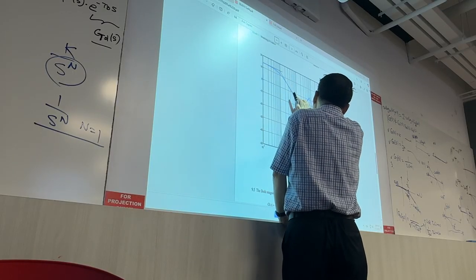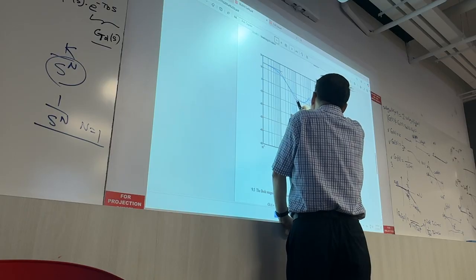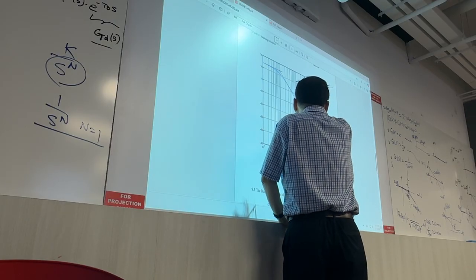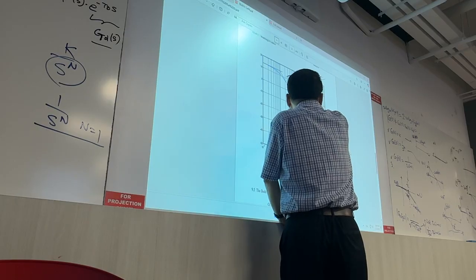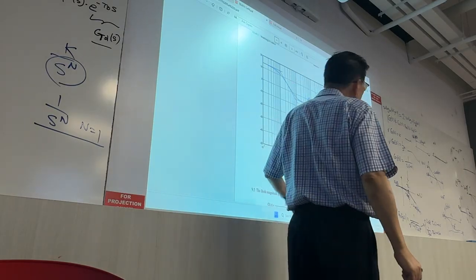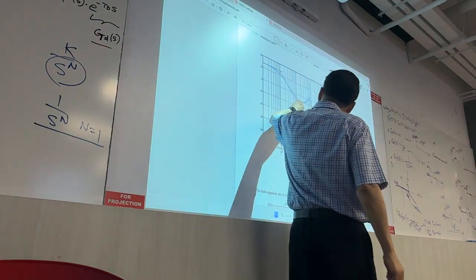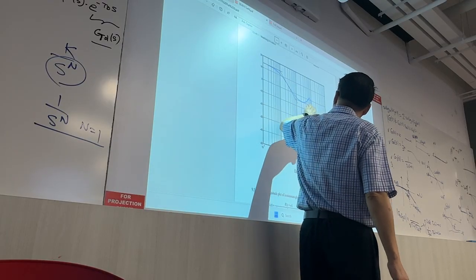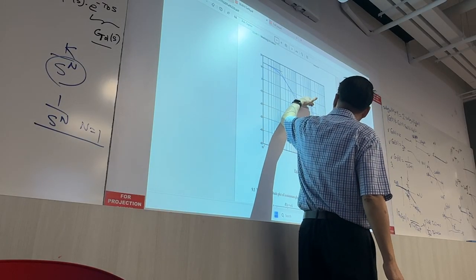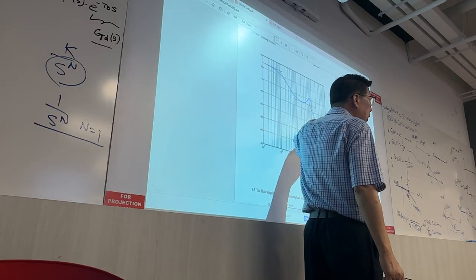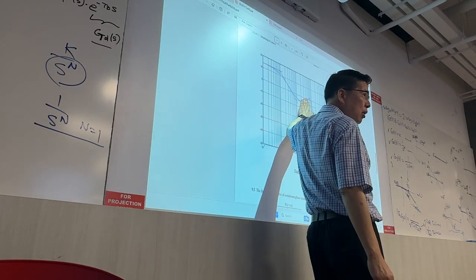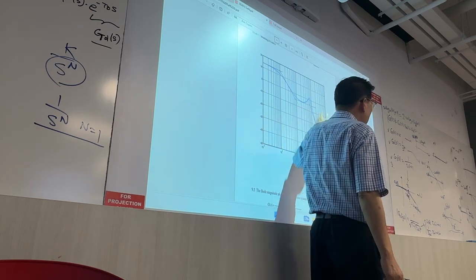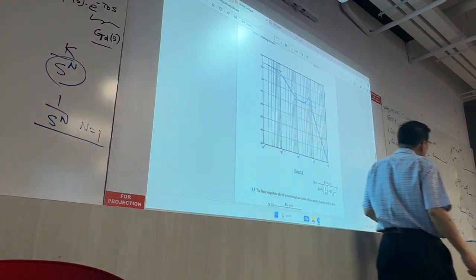then you must stick to that slope, minus 20 dB per decade. And here you can see that it's turning like this, so it looks like a flat. So we use this horizontal one to fit in. And you can see that, in that case, if you have 0 here, you turn to minus 40. Actually, this is a second order system, that means you have a hump, like this.